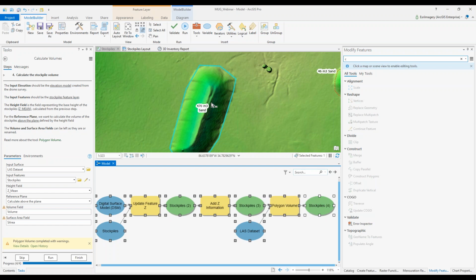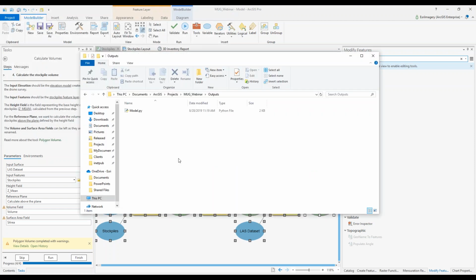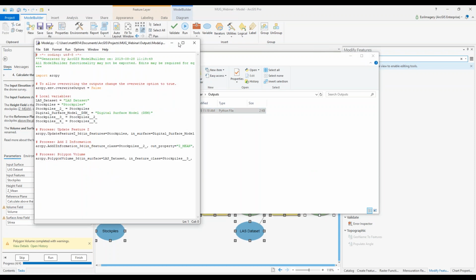Now, for a lot of people, including myself, their first introduction to Python was through exporting from Model Builder in ArcMap. The second enhancement I wanted to highlight with Model Builder is that at version 2.4, we introduced that equivalency from ArcMap, which is the ability to export your models to Python so that you can go further and extend this into a Python tool. So from my model at the top, you'll see we've got two options, export to Python file and send to Python window. I can go ahead and do that and open up my Python file within my files here.